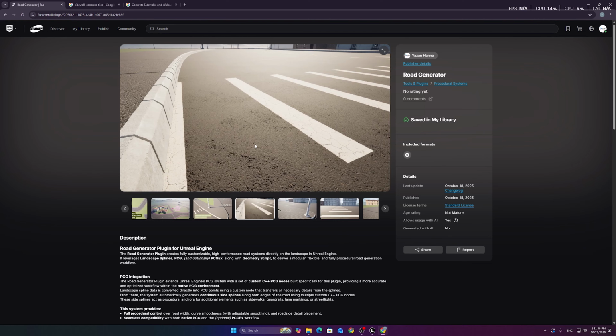Now you can do this also with static meshes, but with static meshes you will need a lot of triangles to get so much detail out of the displacement map, and this will cost you a lot in performance. So doing it on the landscape directly with the landscape splines will allow you to add a lot of details without costing too much in performance.